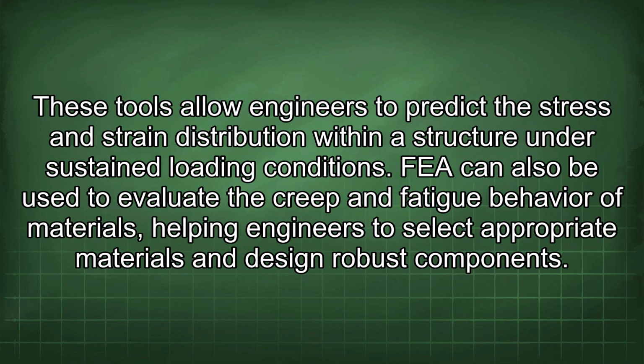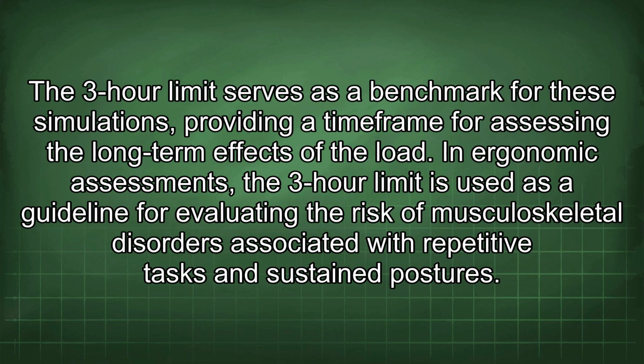These tools allow engineers to predict the stress and strain distribution within a structure under sustained loading conditions. FEA can also be used to evaluate the creep and fatigue behavior of materials, helping engineers to select appropriate materials and design robust components. The 3-hour limit serves as a benchmark for these simulations, providing a timeframe for assessing the long-term effects of the load.